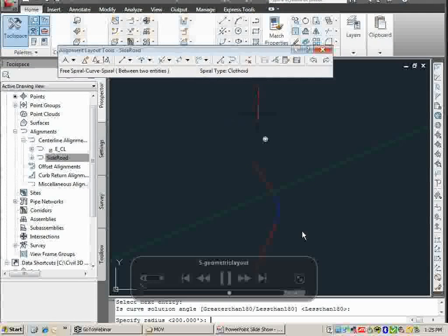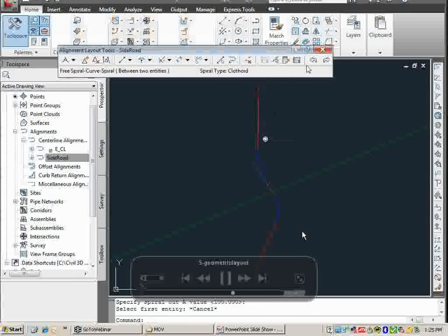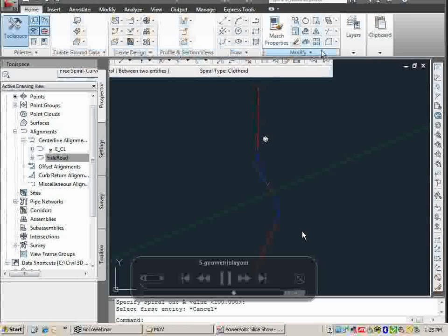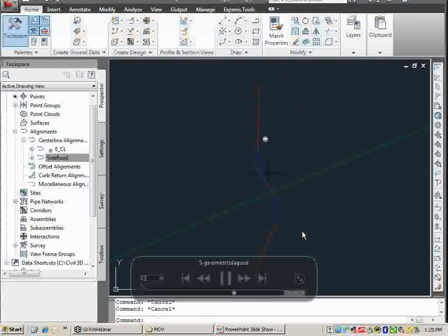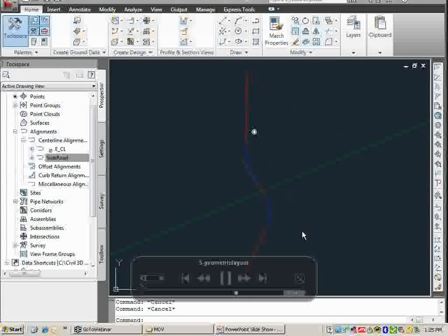And as part of any of your engineering, you have to be able to put in engineered curves in that. And again, that's what Civil 3D excels at. It's got PI-based, element-based, best fit-based, COGO-based, every type of alignment geometry you can think of to do your work. So if you need to come in and set a point on the roadway, it's very easy to set it and then turn a deflection angle and then fit the geometry.